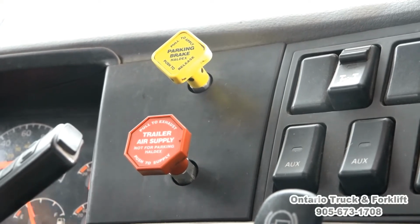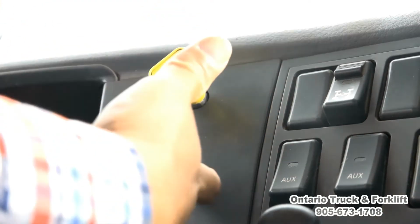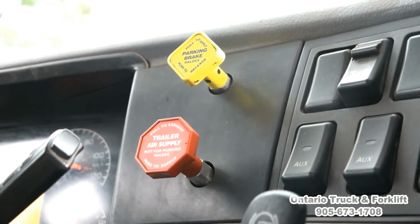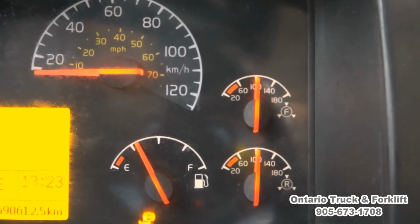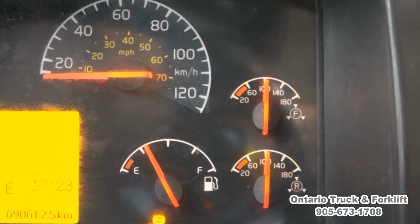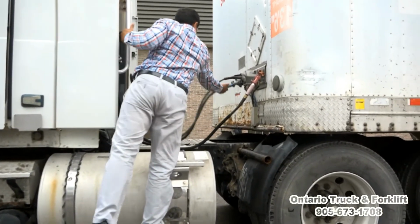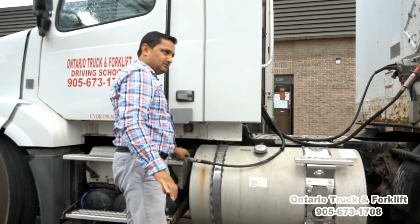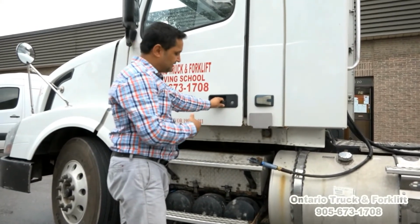Now we are checking the tractor protection valve. For that, we have to make sure our parking brake is in the released position, the trailer supply valve is pulled out, and our pressure is 100 psi or above. Now we will go down and remove the service line from the trailer. We pull the service line out and keep it close to the cab. Then we go inside, press the brake pedal, and listen for a leak.